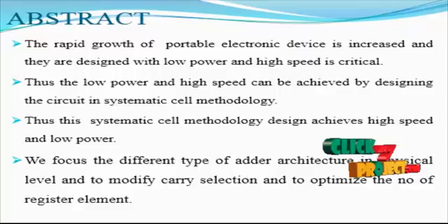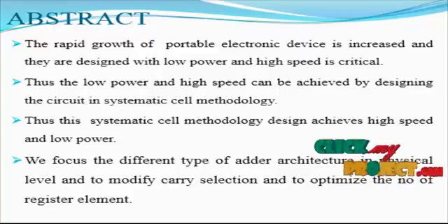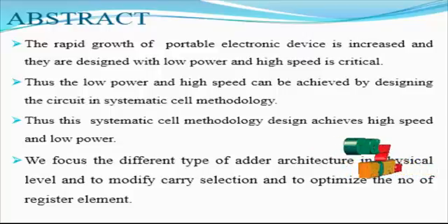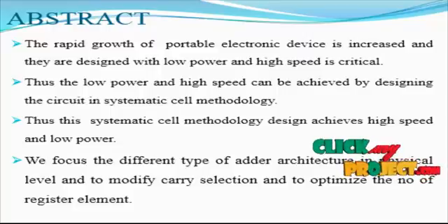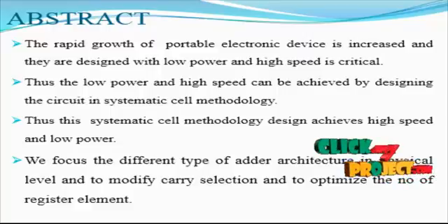At first, priority is deliberately given to general design goals in the basic structure of the circuit. This structure is generated systematically by employing the binary addition diagram. After that, for high flexibility in the design targets, SCDM aims at specific ones in the remaining 3 steps, which are wise selection of basic cells and aided mechanisms as well as transistor sizing. In the end, the outputs perform well with supply voltage scaling and their critical path contains only 2 transistors.